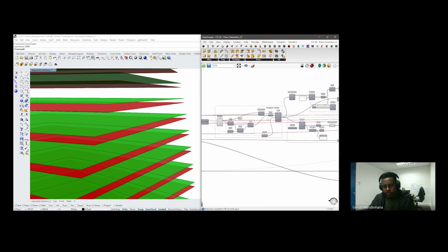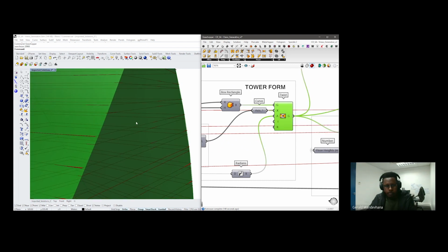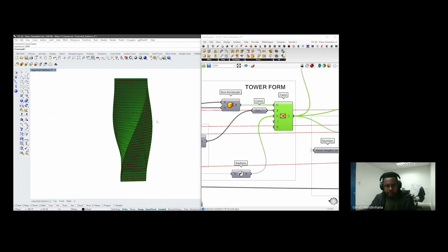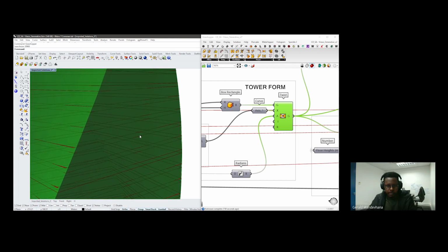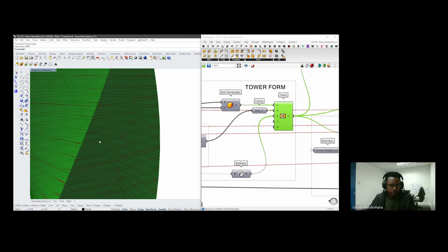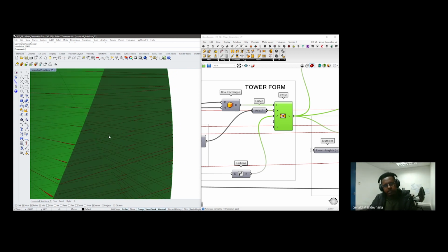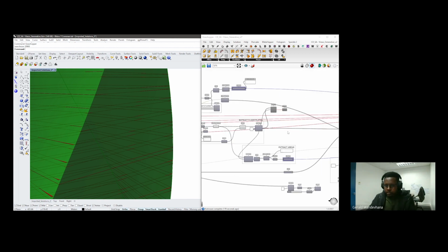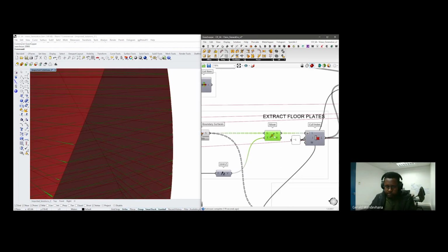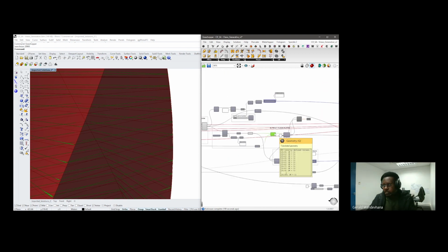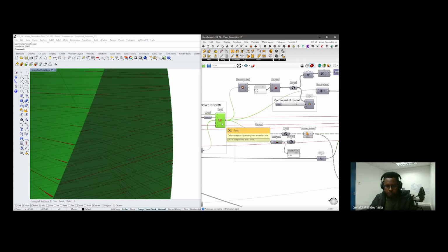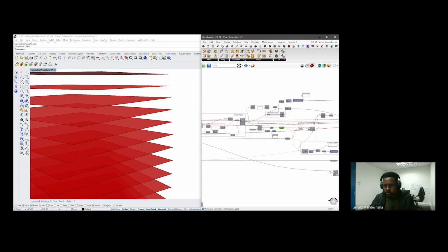And if we even go further and try to articulate this building more, our assumption right now is the building is fully glazed, but typically in every high-rise building, from the finished floor level to around 900 millimeters, maybe it's an opaque surface, and then you have your glazing starting from that level to like 2.1 meters, 2.4 meters, or whatever it is. So it's important to set the parameter of this height so that you're trying to simulate something which is closer to reality than not.